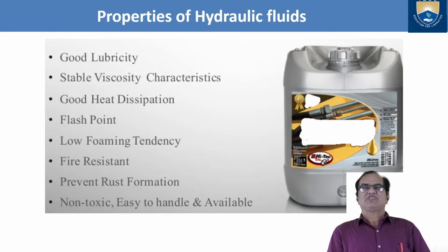It should also have stable viscosity characteristics as per the temperature of the surroundings and the system. Your hydraulic fluid should behave in a proper way. Good heat dissipation. It should dissipate the heat absorbed during operation, otherwise the temperature will be high and a fire will take place.